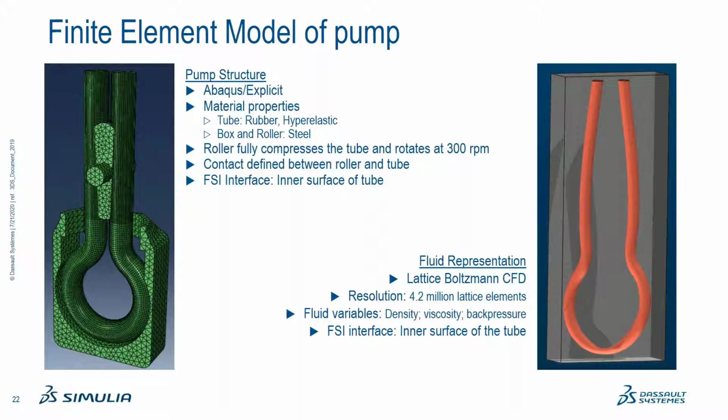The two domains, structure and fluid, were numerically coupled together to capture the effects of fluid on structure and conversely structure on fluid. So even though you appear to be looking at two models here, it is in fact only one model with two domains, coupled at the fluid structure interface, which is the wetted inner surface of the tube.